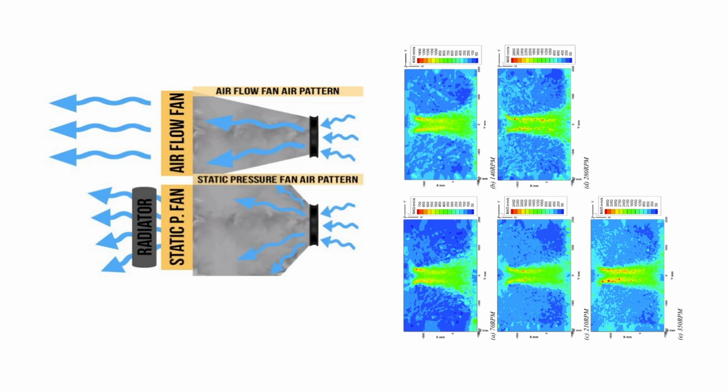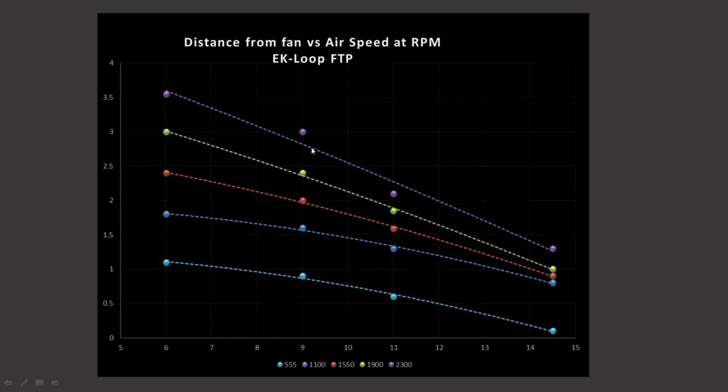So this would be a front mount type radiator I'm talking about. If one is on the top, you still want good clean airflow going through your case, but again, it doesn't quite matter as much, because you're just going to be using the radiator to suck the air out anyway if you're doing it chimney style. The only exception is if you're using a back mount radiator, so it would be a 120 or 140 single fan rad, which aren't really recommended, but if for some reason you are doing that, then the airflow going through the case really does matter. So that's just a quick explanation of why this actually matters in terms of case airflow.